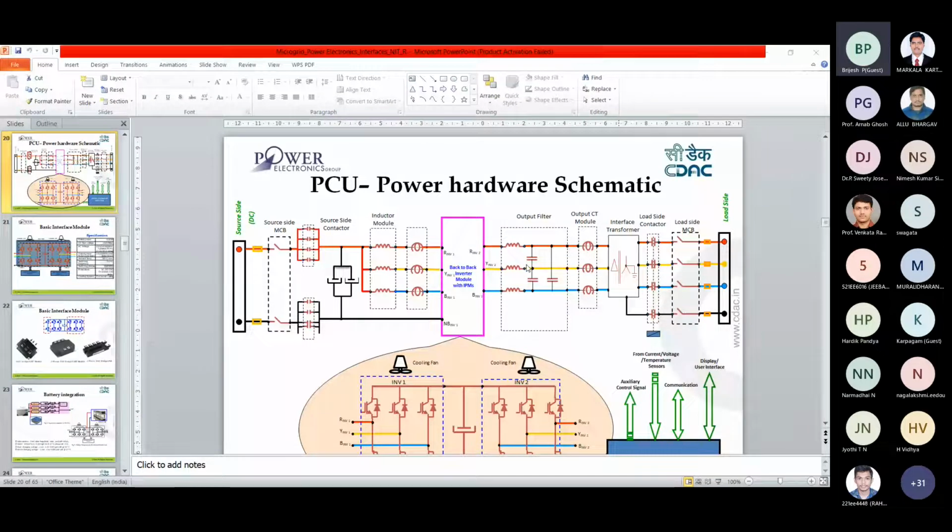So the battery used is a maintenance-free battery, from Firefly. The capacity: we have used 3 sets of 360 volt 100 Ah battery, so that it will work for more than 20 hours from both solar and battery. About 20 hours, more than 20 hours.